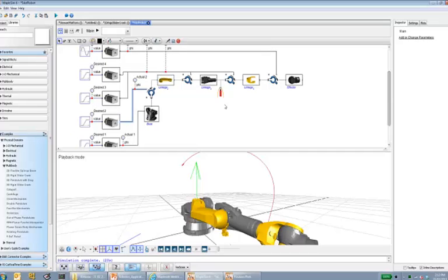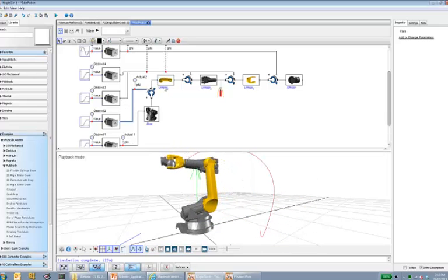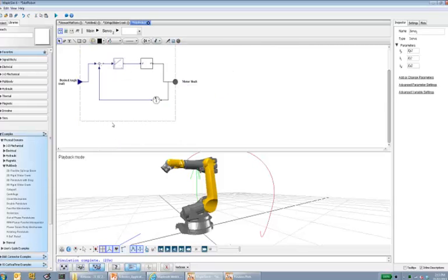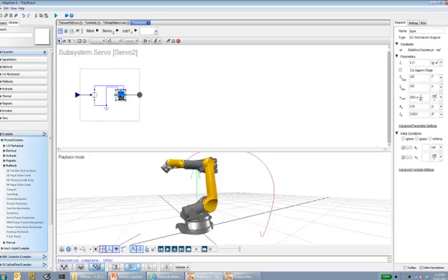Also, this type of simulation is known as physical domains. So the connections between components represent physical connections. These are not input-output connections. Torque and rotation is related between the revolute joint and the output of each electric motor. And an electric motor is an actual electrical component from the electrical library. So you can see that various domains can be put within the same model.